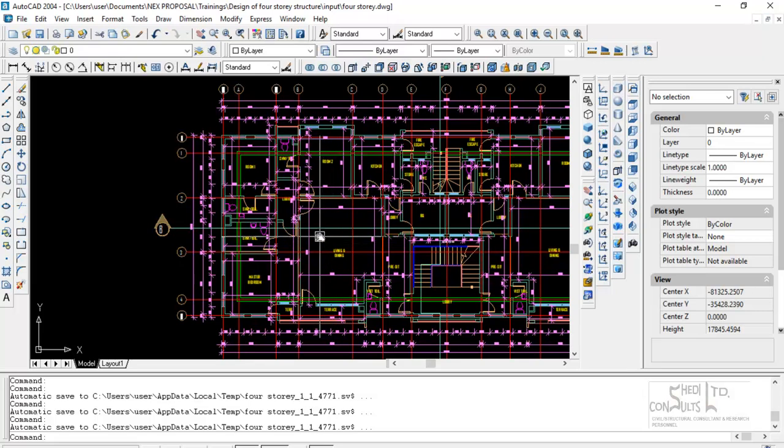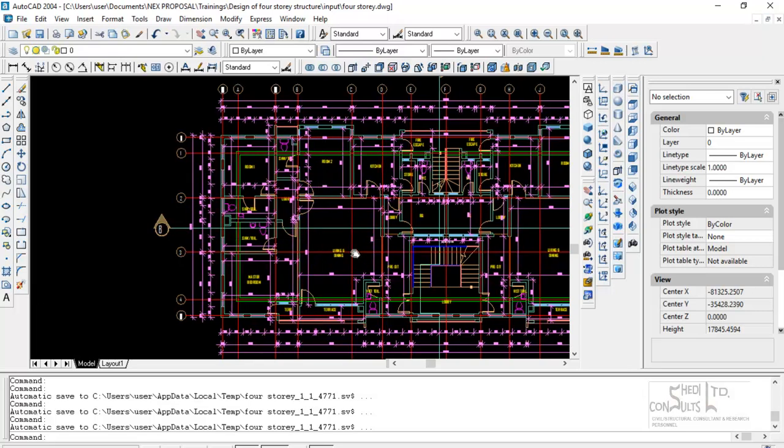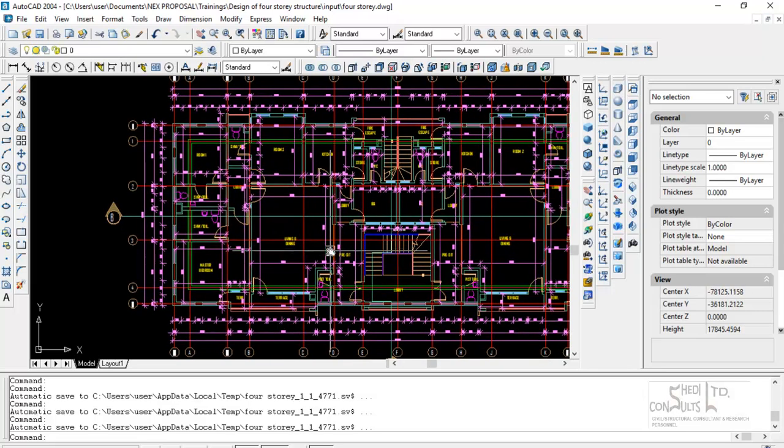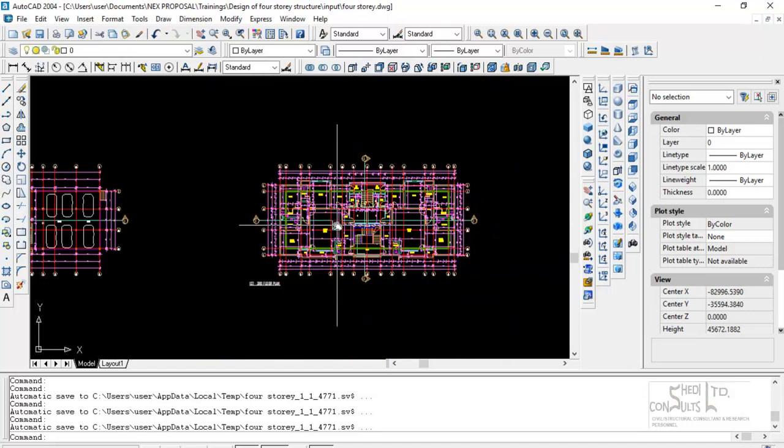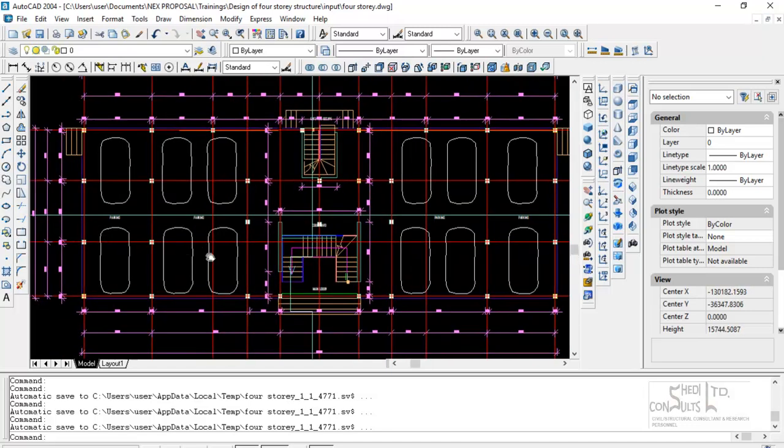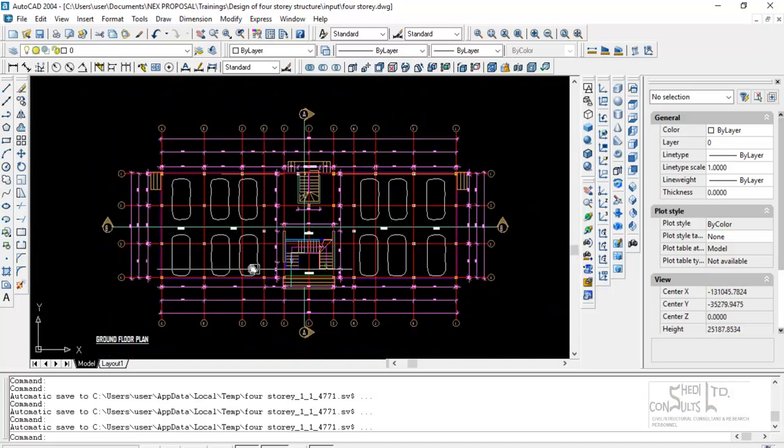This will give us very important information on the gravimetric and shear strength properties of the soil, as well as the plastic properties of the soil and the ability of the soil to undergo plastic deformation. From what we saw on this site, from the geotechnical investigation report, it was clear that the site terrain is filled with, underlain by a very thick layer of peat.